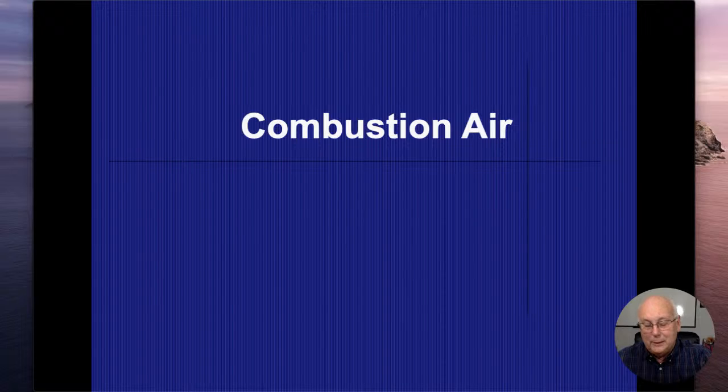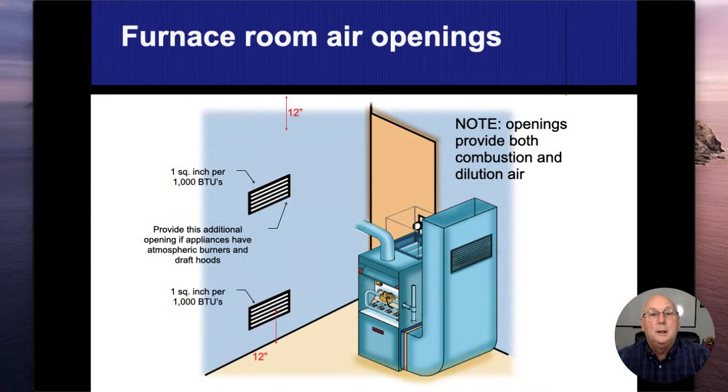Combustion air, I kind of used that term a little bit earlier, but we need to be checking for combustion air as it comes into our appliances to make sure they're working, or our gas appliances. So when I use the term appliances, I am talking about the furnace, the water heater. I'm even talking about a gas dryer or a gas stove. All of those, we're going to lump them together as appliances.